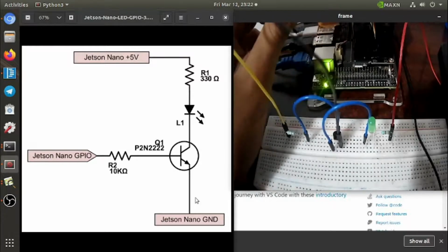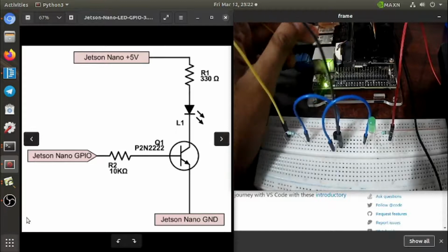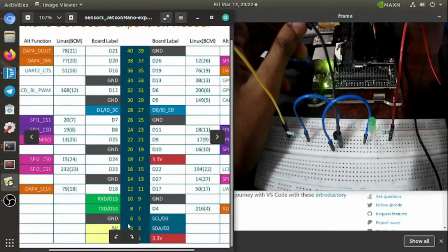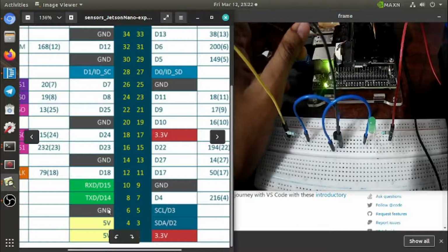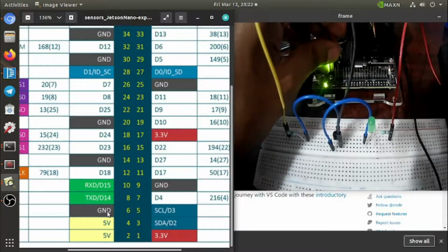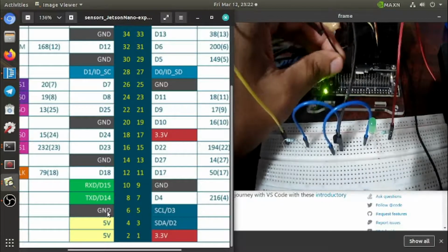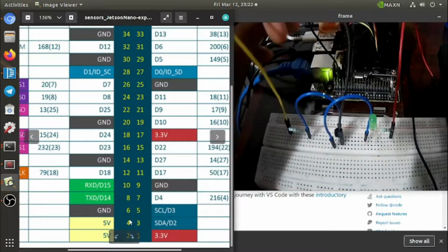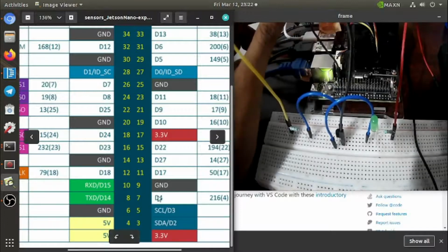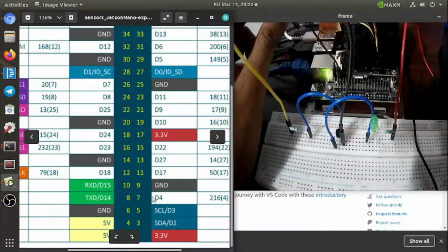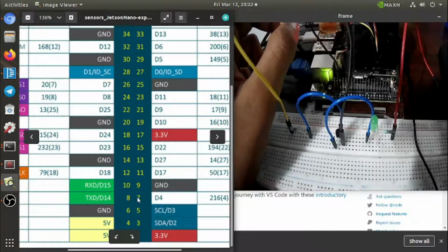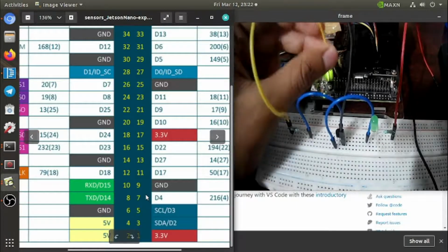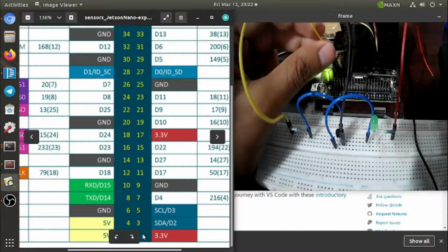To ground we need to put it in the 6th pin. I'll show you. I showed you before that this 6th pin is the GND, so we need to put it in the GND, that is 6th pin, inside 3rd pin. You guys can connect it like this, inside 3rd pin. And then we need to take this, and I told you we are going to connect using 7, or we can connect to 7 or 11 or 13 or 15. Now I'm going to use 7, that is the nearest one. That is outside 4th pin. You guys can count it simply 1 2 3 4.